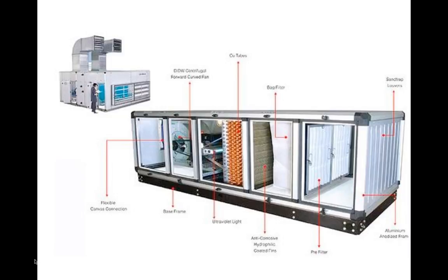If you look at the small version up there in the top corner with the little man there, you can see the far sides. You can see kind of a Venetian blind kind of thing, and that's the damper. That controls how much outside air is coming in that's mixing with the recirculated air that's also going into the beginning of this air handler. Those units you see at the top are exhausts, how much exhaust air is being dumped out while you're pulling in that fresh air as well. So that's what a big air handler looks like.